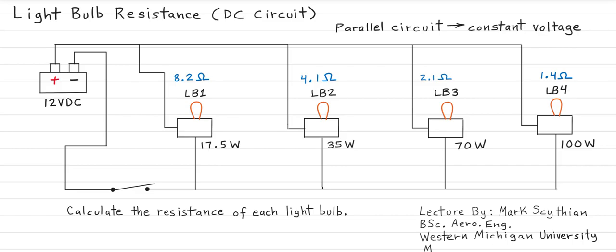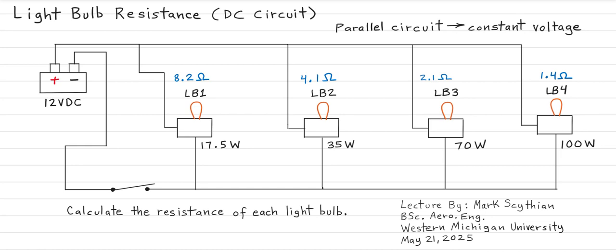And so sometimes you can't just rely on what's in the book, and you sometimes can't rely on what is just in the multimeter ohms reading. You may have to look over the schematic and then individually test your ohm meter from positive to negative here. And let's say the information is validated as correct, you should be getting 1.4 ohms on your ohm meter.